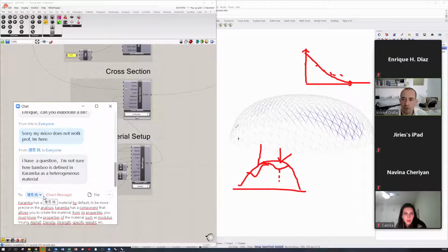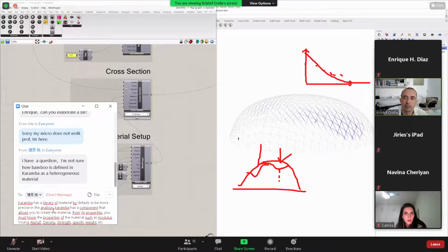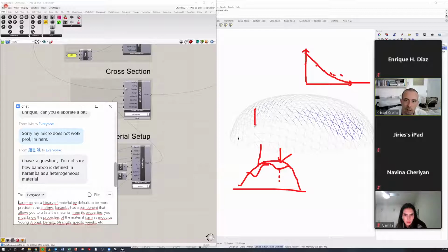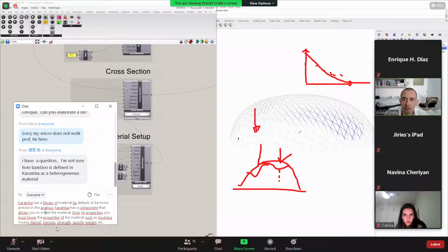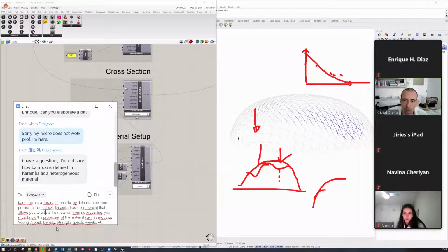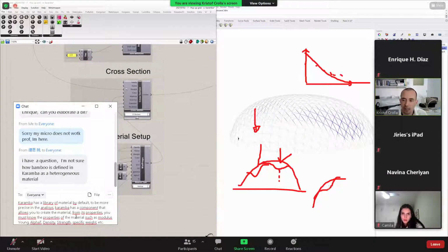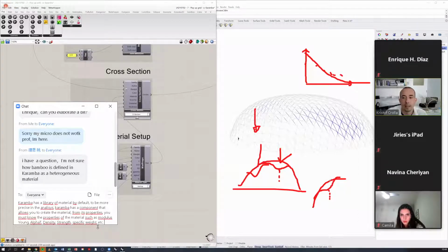So what they would do on site is, of course, calculate and test ahead of time on small-scale models, but then once it's built, they would take a few points, add water or weights to see when the shell goes from a bubble like this to something that buckles in. The values from that local failing would then allow them to extrapolate to the whole shell.